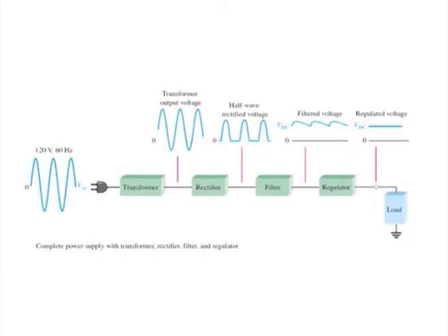The voltage produced is used to power all types of electronic circuits, including consumer electronics, computers, industrial controllers, and most laboratory instrumentation systems and equipment. The DC voltage level required depends on the application, but most applications require relatively low voltages. This basic block diagram explains the components of the complete power supply. It consists of a transformer, a rectifier section, a filter, and a regulator.